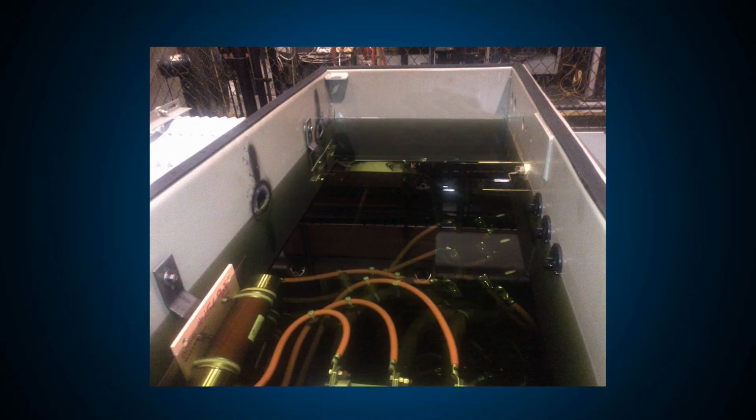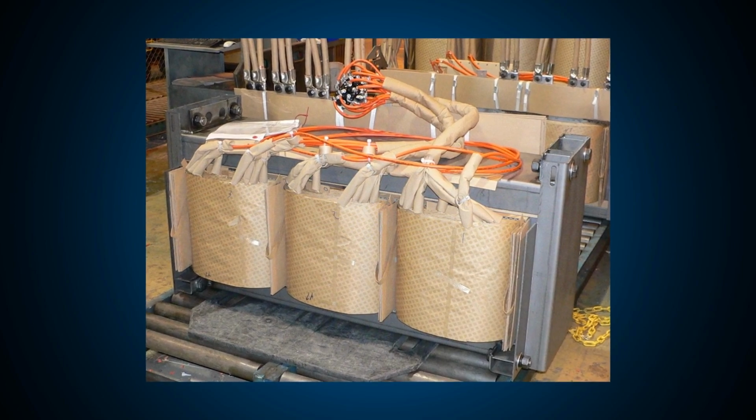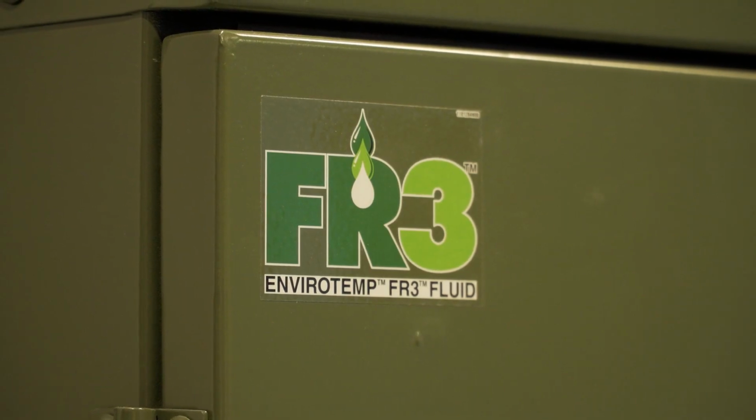Although a typical transformer has no moving parts that may wear out over time, a transformer will age and become increasingly susceptible to failure due to dielectric breakdown. The insulation paper used in the coils of a transformer, along with the fluid in the tank, are the two main materials that provide the dielectric strength between the live parts of the core coil assembly and ground.